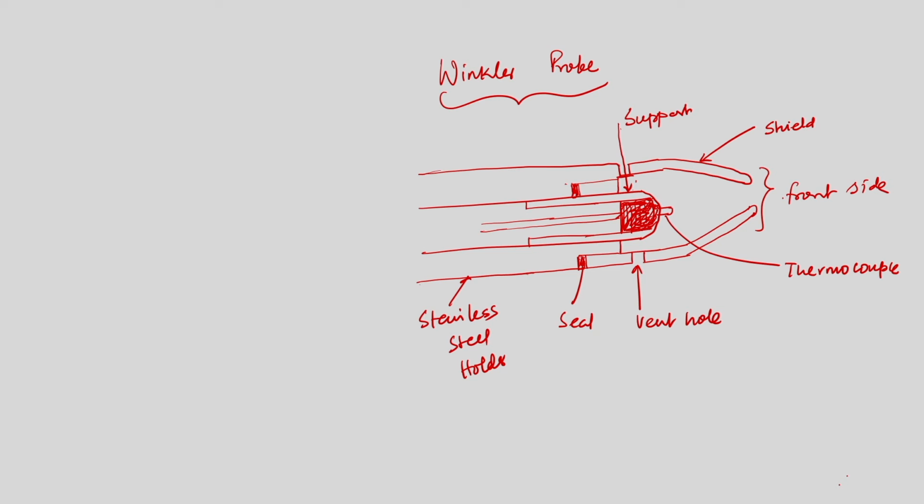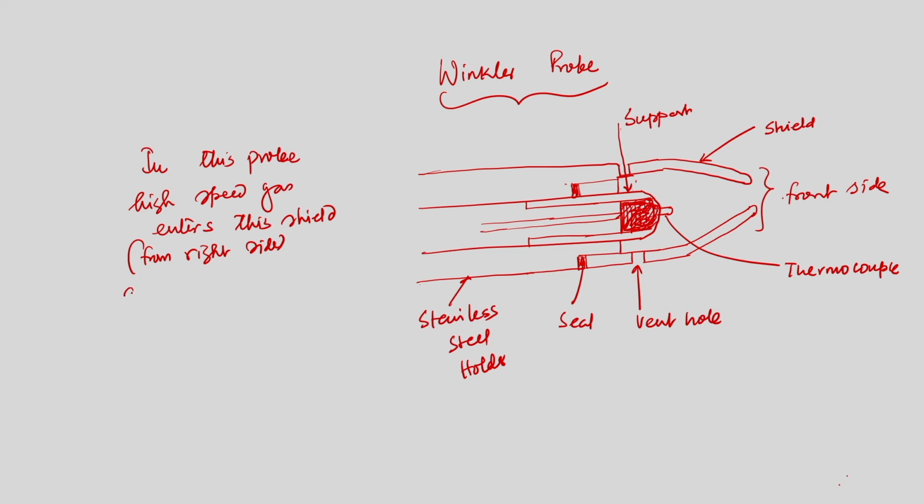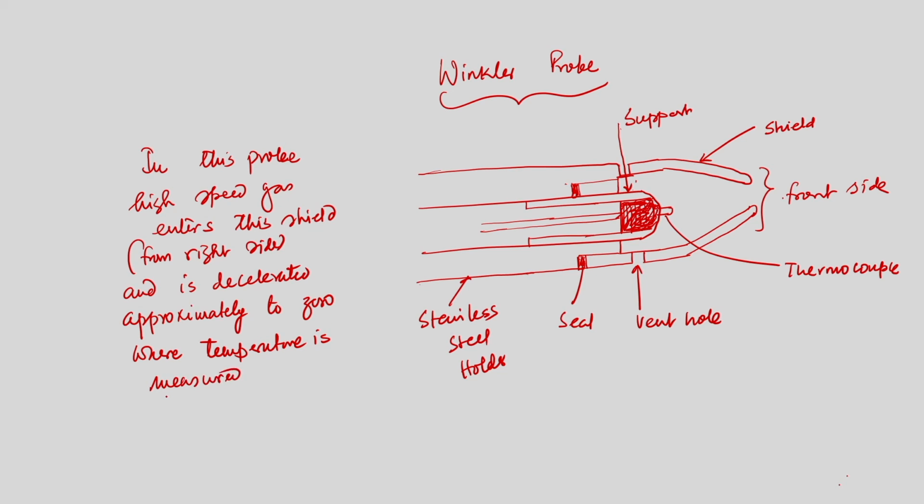So, what we can see in this probe is that high speed gas enters this shield from the right side and is decelerated approximately to 0, where temperature is measured with a thermocouple.